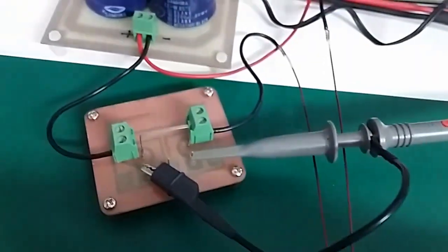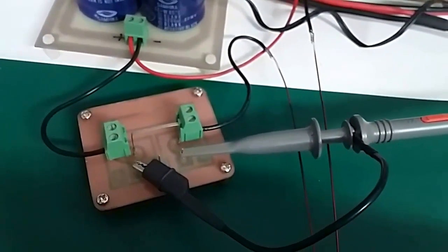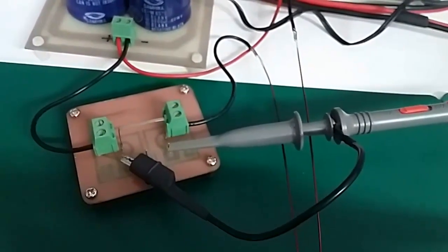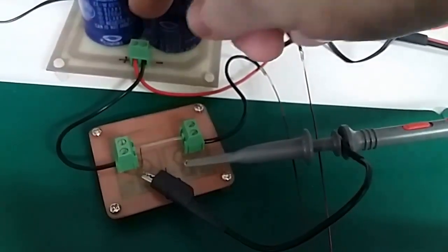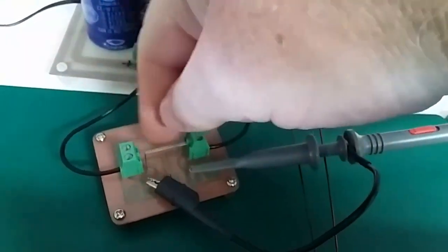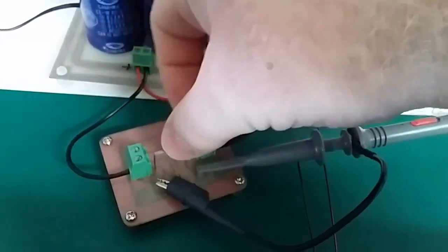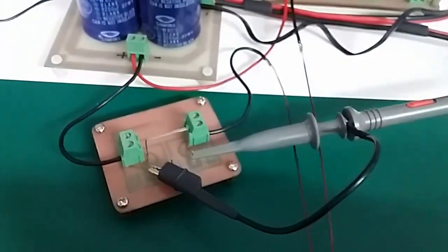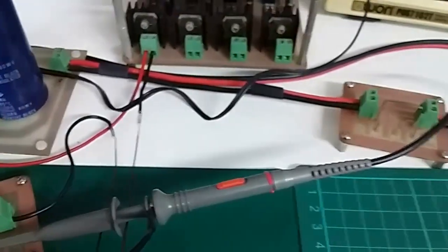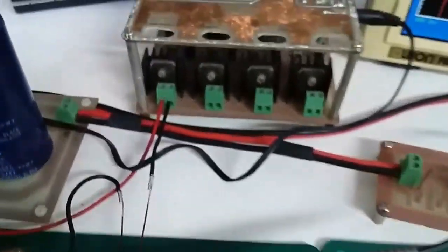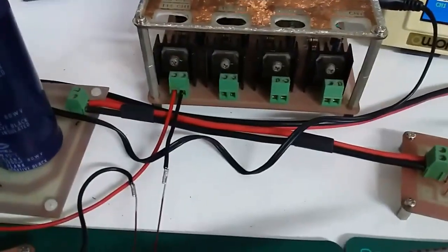Okay, what I've done is I've put a measurement block on the cold side of the coil. And we have obviously negative to ground through our little resistor here. These things are fantastic, worth their weight in gold. If you haven't got one, build one. Very easy, very simple, very good. Same as before, switching via that channel.